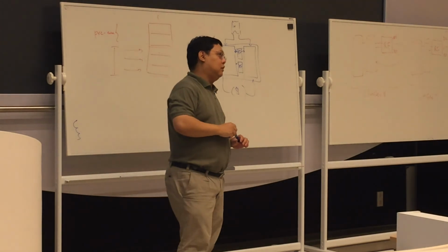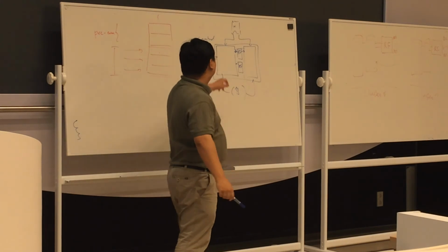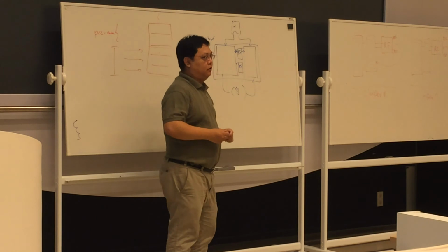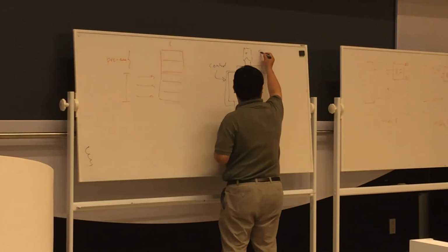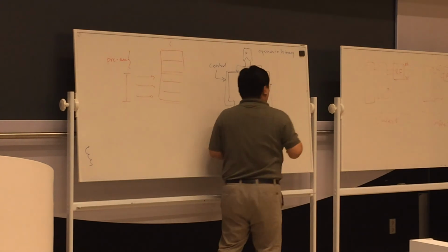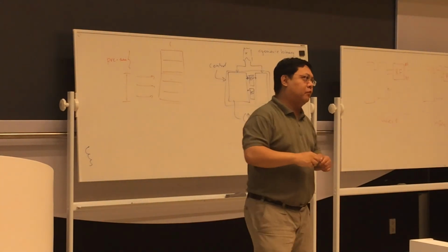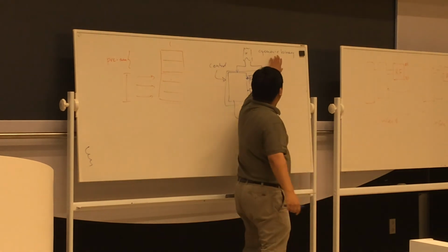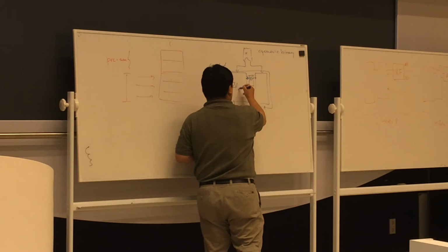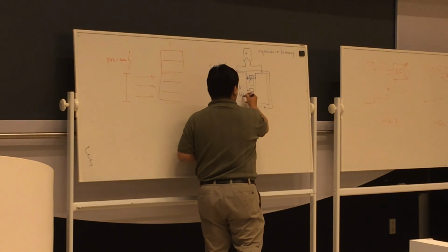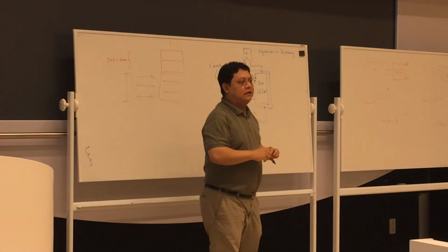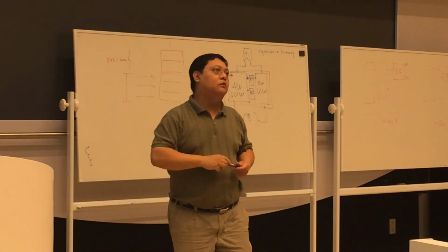Is it the compiler that has to manage this? No, the nice idea about this is that the compilation that we have is the same for both programs. That's something we call generic binaries. It's a way that we compile the program so that it can run in 4-way mode. So this is a 4-way VLIW, and this is a 2-way VLIW. And it's exactly the same code that we run.